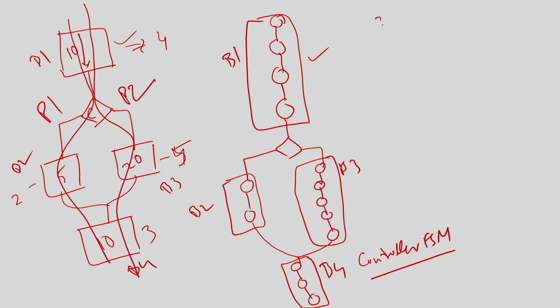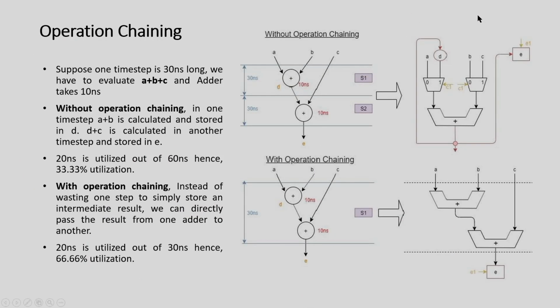So, now there are 25 operations in path 1, and in path 2 I have 10 plus 20 plus 10, 40 operations, right. So, now what we can do is schedule path 1 independently. If we try to find the minimum number of timestamps needed for path 1, since I can share timestamps between operations of two different basic blocks if they are not data dependent, I can probably schedule this in, say, 7 timestamps, okay.